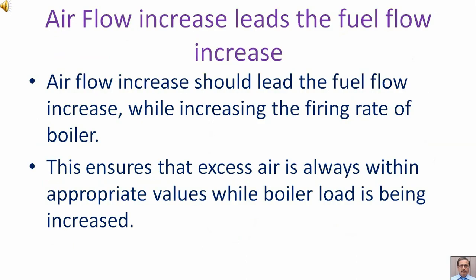Airflow increase leads the fuel flow increase. Airflow increase should lead the fuel flow increase while increasing the firing rate of boiler. This ensures that excess air is always within appropriate values while boiler load is being increased.